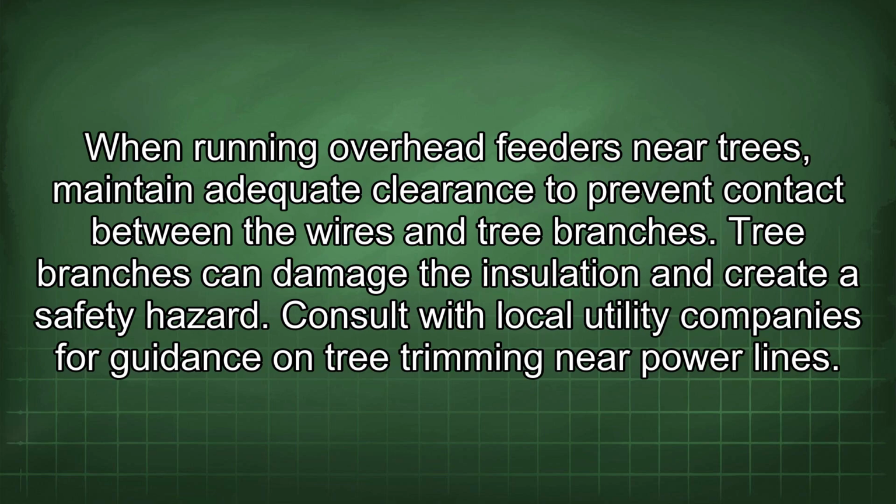When running overhead feeders near trees, maintain adequate clearance to prevent contact between the wires and tree branches. Tree branches can damage the insulation and create a safety hazard. Consult with local utility companies for guidance on tree trimming near power lines.